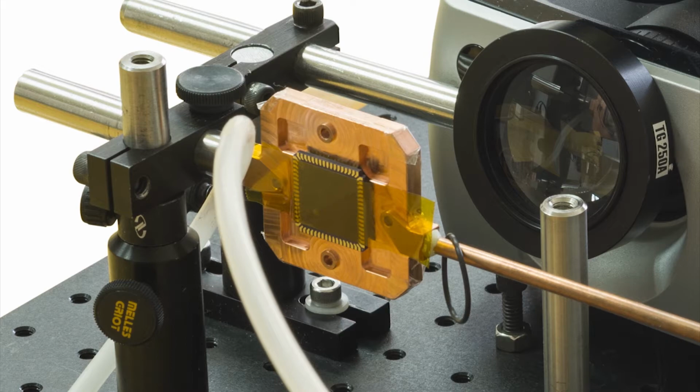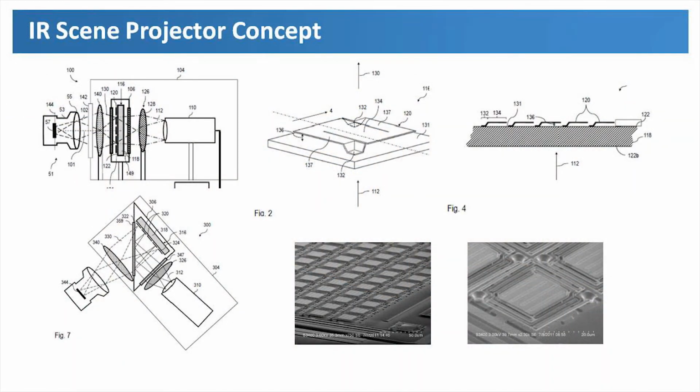Thus, the operation of the chip depends uniquely on its architecture, and in particular, for each individual pixel, it depends on the support of each of the micro platforms. So again, there is no electronics underneath each pixel. The chip is completely passive and really works like a converter. It converts the visible image to the infrared image in both wavelength bands. It can be made wideband, in the sense that it emits radiation both in the mid-infrared as well as the long infrared, but it could also be narrowband. It could be tuned to one of these two bands, and everything depends on its architecture and generally the design.